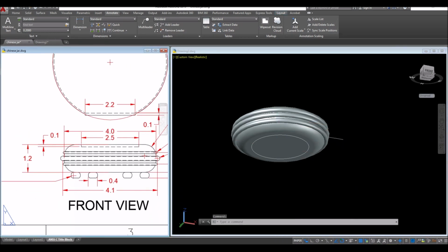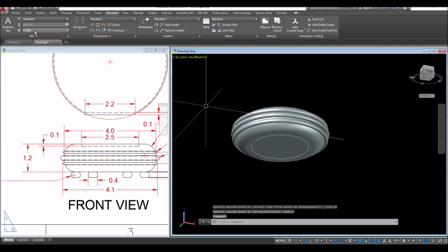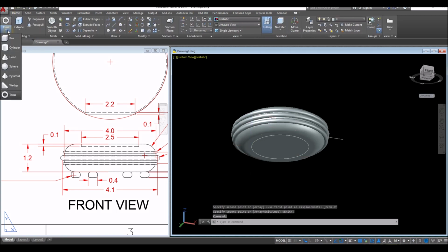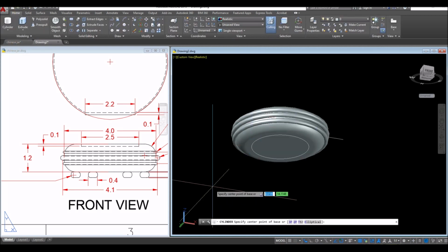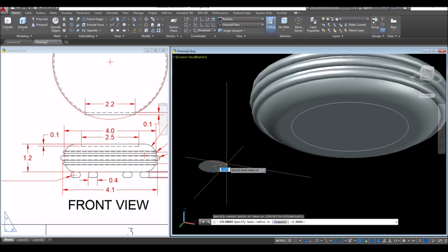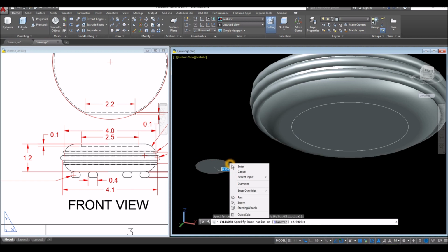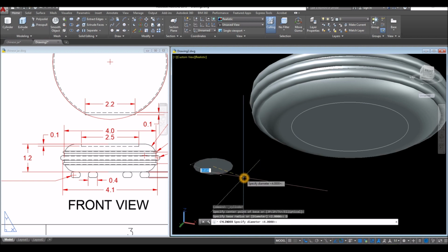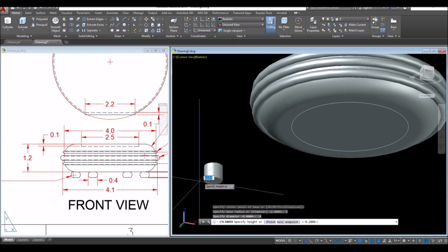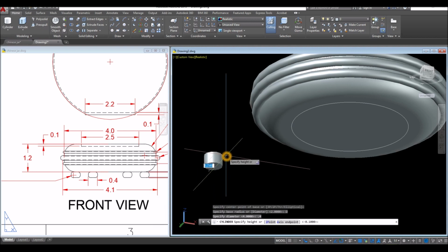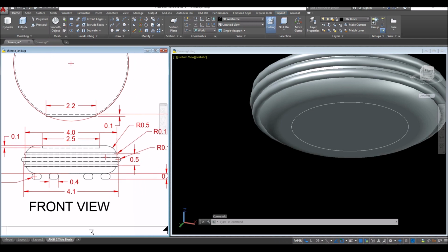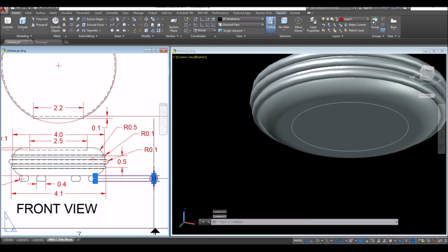So what I use here is also cylinder. So go to home, click this drop down arrow and select cylinder. Click anywhere on the screen. And for the diameter, just right click to select diameter option and enter 0.4. And the height is, oh wait, here. Height is 0.3.